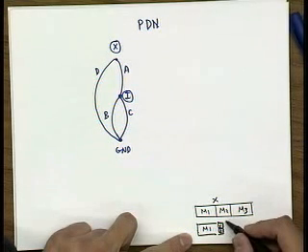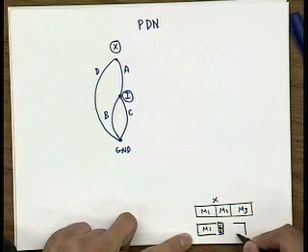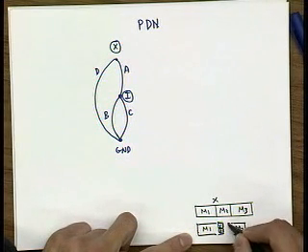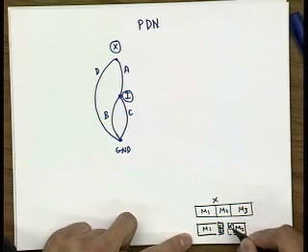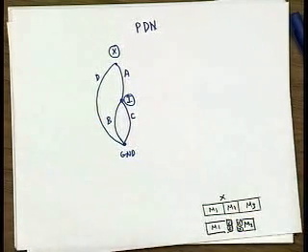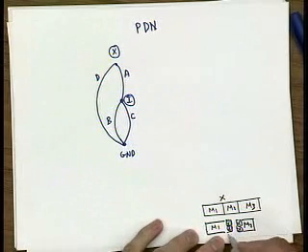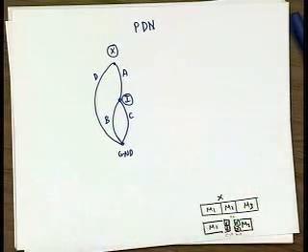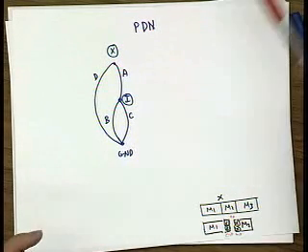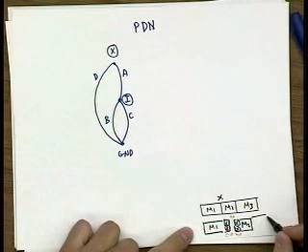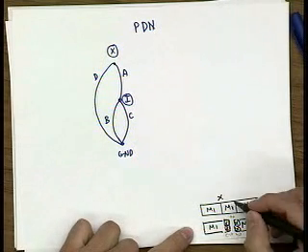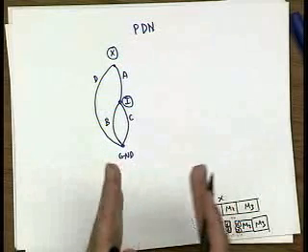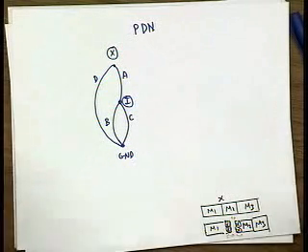Then you have to make a break a little bit, and then you have this M2. And then again, you have to create some contacts. The penalty that you pay in area is all this contact penalty plus any extra space over here, which results in an overall wider standard cell than in this case. So the goal is to minimize the width and achieve the highest compaction in area so that you can have the best density.